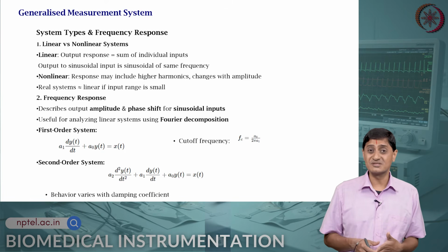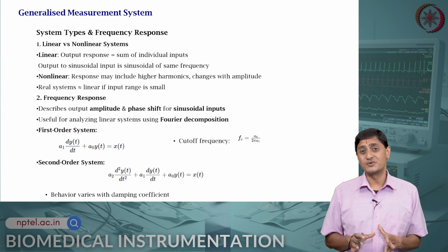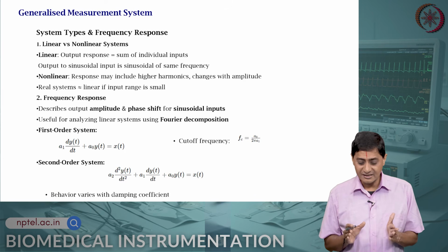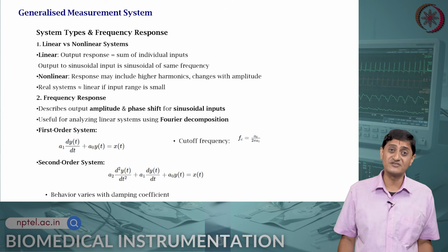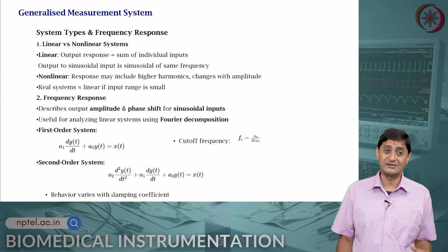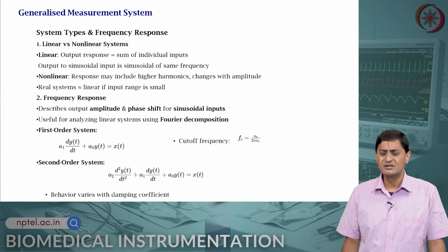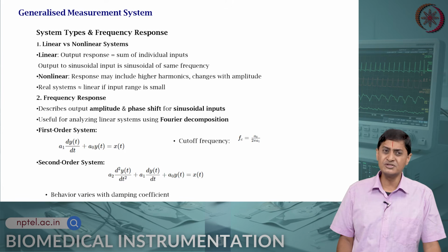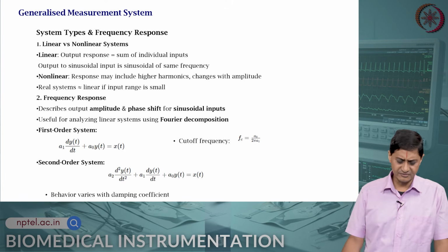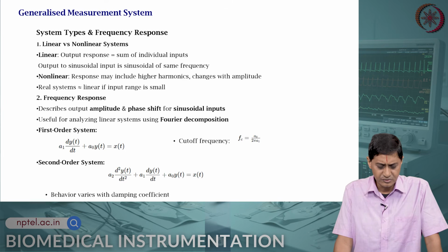Different measurement systems may be specialized for different frequencies, and you are interested in keeping that dynamic range. Which means that you need to understand the physiology, physics and the frequency response very clearly. Frequency response essentially refers to amplitude and phase shift for sinusoidal inputs, useful for analyzing and characterizing linear systems using Fourier decomposition.